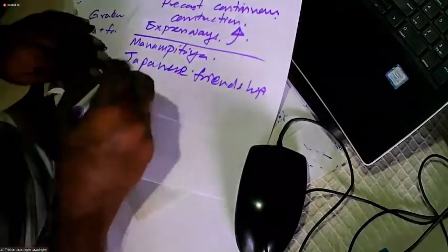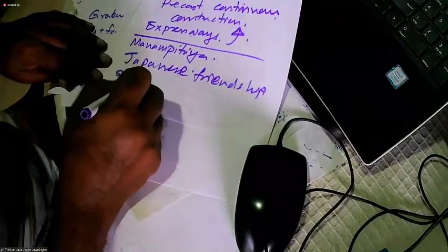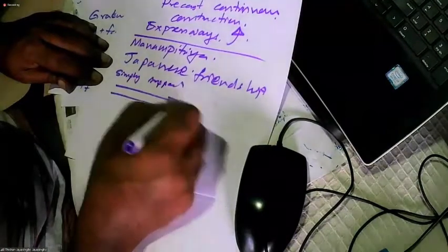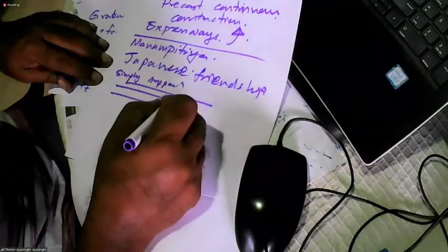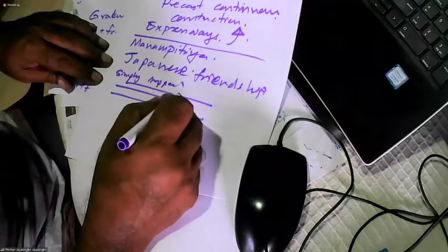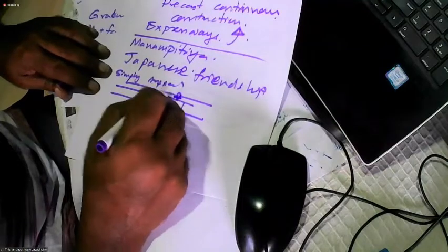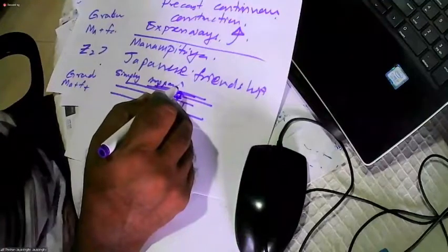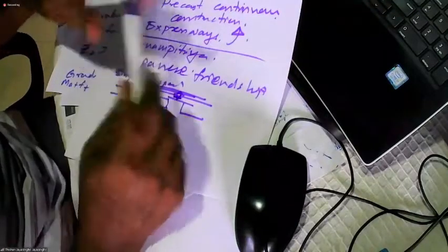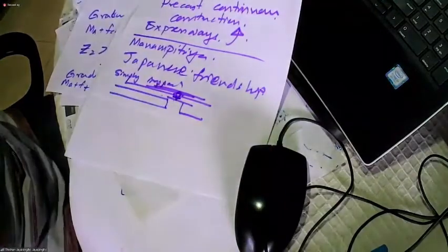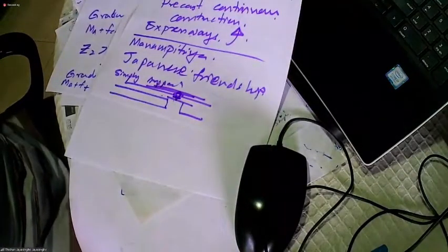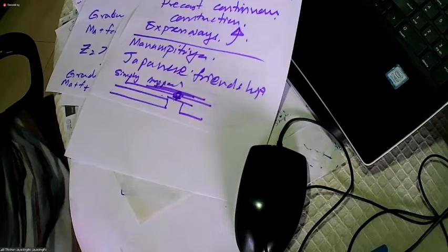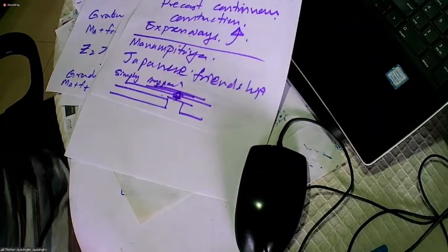And Urugodawatta flyover is simply supported. But we did a trick. What we did was we made the slab continuous and cut a groove. We have dowels there, and we filled up the groove with polysulfide. And then we put a geotextile on top of that, and then did the carpeting. So because of that, you don't see any joint there, but it's not a continuous structure. It's a precast simply supported construction. You don't see the expansion joints or contraction joints. You feel that it's a continuous construction.